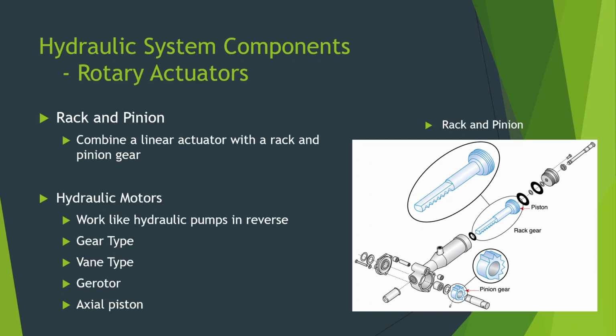And they do not have the variable inclination that the pumps have, that constant pressure variable flow. The swash plate is at a fixed angle because they're designed to operate at a certain speed. There may be some variable speed ones out there, so you can use a swash plate to adjust the speed, but for the most part, they're a fixed swash plate in order to run at a certain speed. And so that's going to be the most common.